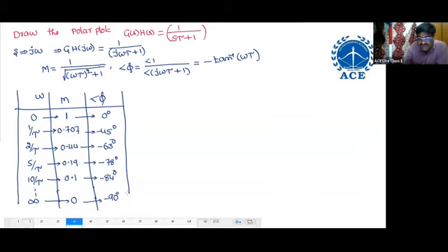That's why we'll go by one shortcut procedure, after solving another two problems, so that directly we can draw the polar plot without much calculations. But any doubt comes, you go by the standard procedure. A virtual calculator is there in the GATE exam. You can go by standard procedure. Nothing wrong.